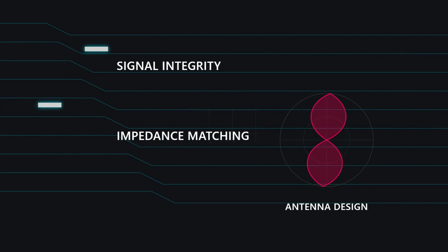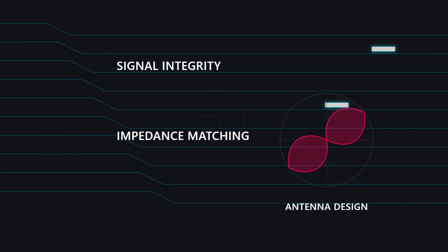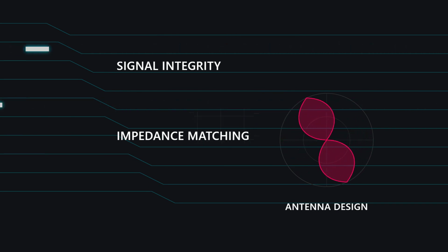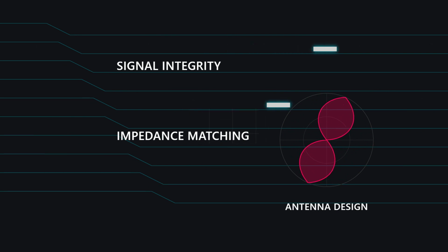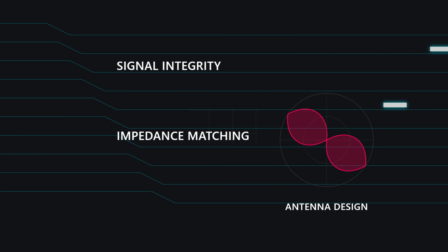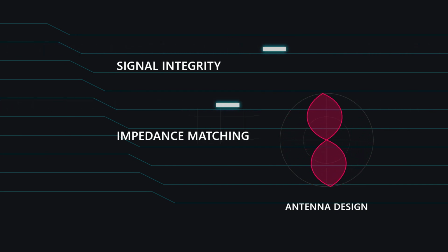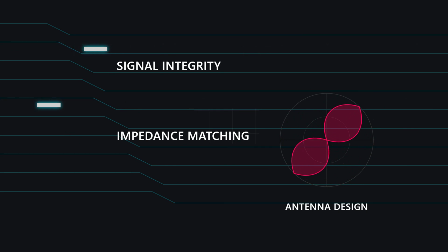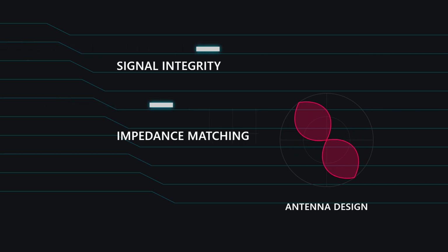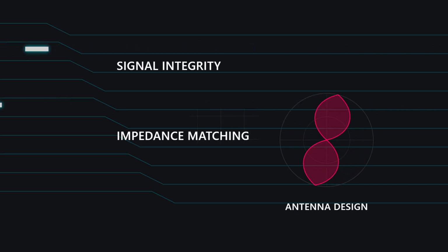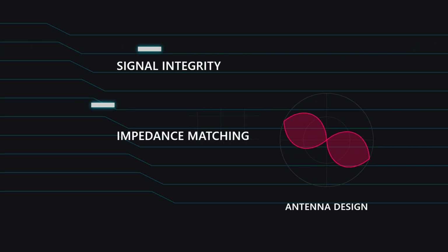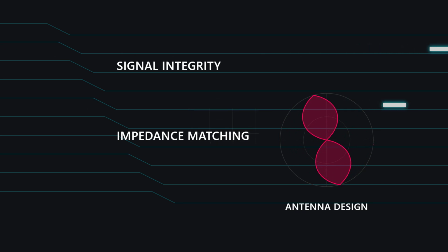Maxwell's equations are the absolute foundation for analyzing signal integrity in all high-speed digital circuits. Transmission line theory, which governs impedance matching and the minimization of signal reflections on printed circuit boards, is a direct mathematical consequence of the electromagnetic wave equation. In microelectronics design, advanced electromagnetic simulation tools utilize these equations to accurately model complex phenomena such as crosstalk between adjacent traces, noise propagation within power delivery networks, and the radiation patterns of integrated antennas.